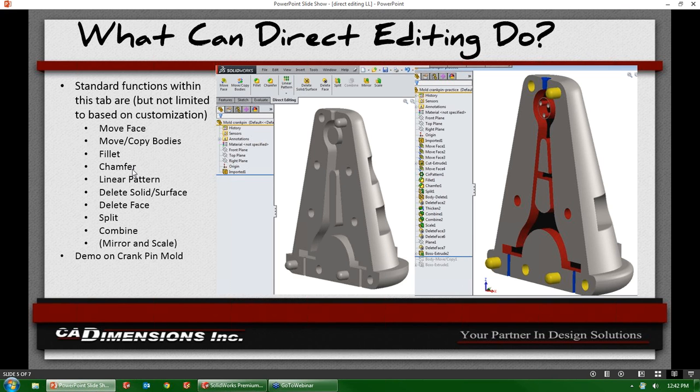The chamfer we use to add some draft to an existing part. We did a circular pattern instead of a linear pattern to get this series of circles inside our connection circle. Delete face originally turned this into a surface, which we then thickened. We also used delete face to fill up this hole and this recess.